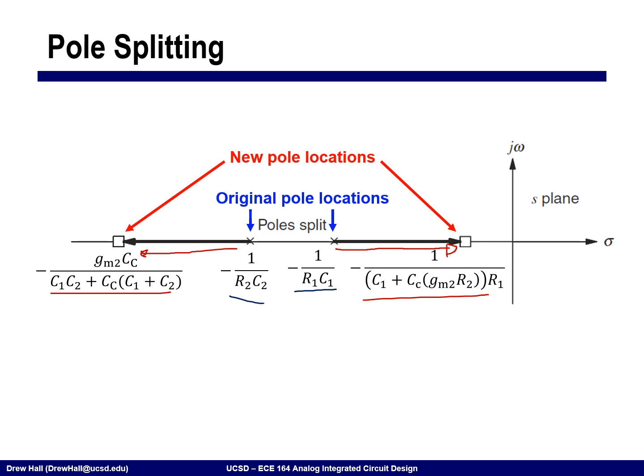If the two poles move together, and they both move in, I would not do anything to my phase margin. My phase margin is all about the difference in frequency between these two poles, okay? So it's really important that we're able to position them separately, but even better that we can do one going in and one going out.